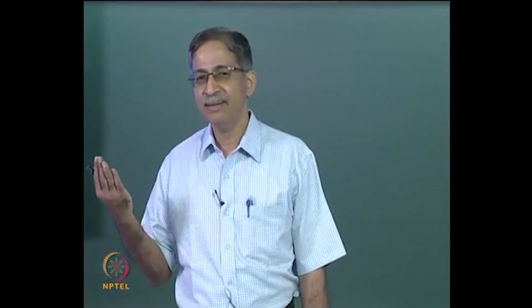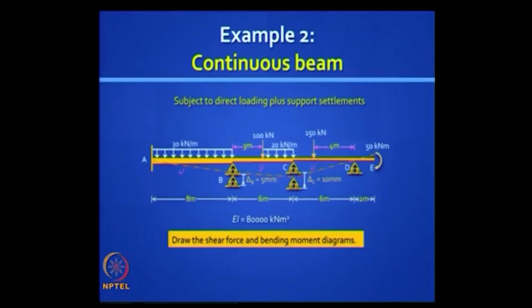What is the first thing we will do? First we will simplify our work. So we will get rid of the overhang because it will unnecessarily bring in more coordinates. We want to minimize our work, so you do that. But still, even after doing that, what is the degree of static indeterminacy? 3, right? Just think of the primary structure. What primary structure is most comfortable for you? Cantilever. So cantilever means 3 props you have to throw away, right? That is the easiest way to understand.